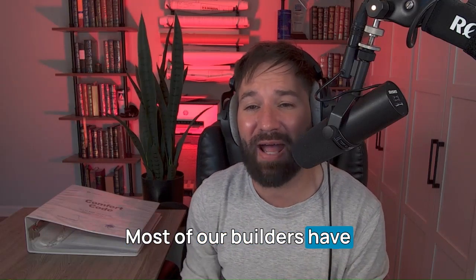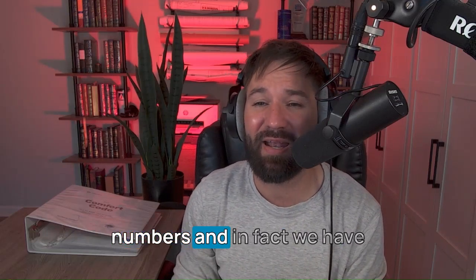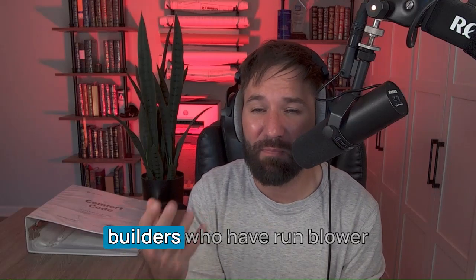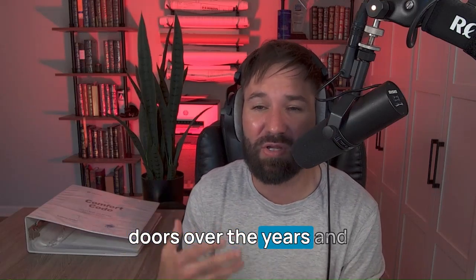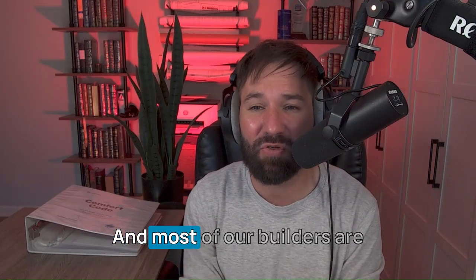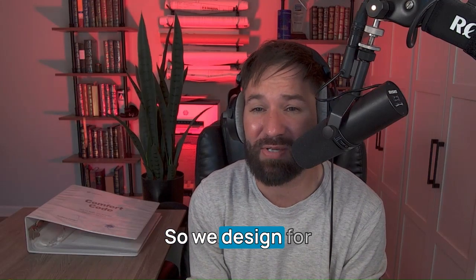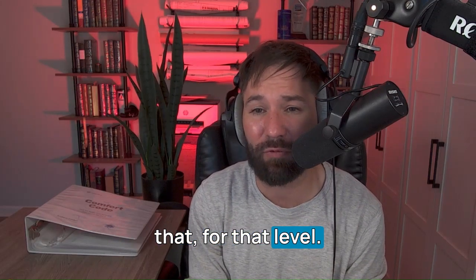Most of our builders have committed to certain numbers. And in fact, we have quite a bit of data sets from builders who have run blower doors over the years and given us that information. And most of our builders are building houses at a 3 to 4 air change level. We know that. So we design for that level.